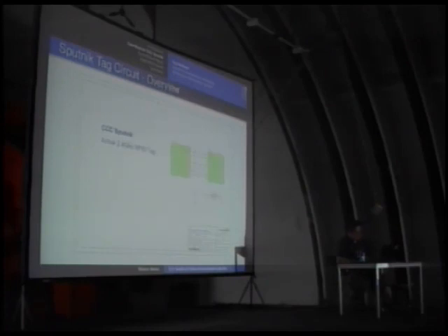If you have a line, then the line is automatically connected if it shares the same name. So this makes a sheet more reasonable. If you have a line here that's IRQ, it's automatically connected to another line that is also called IRQ, if it's on the same sheet. This ensures that you don't have wild crossings between all kinds of lines and you lose completely track. So first look at the names for the lines and then you see where they go.